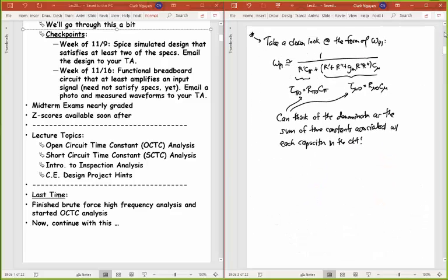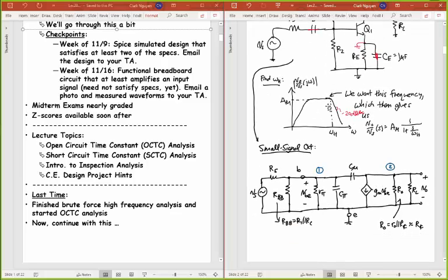We're looking for this frequency cutoff here, the high frequency cutoff. Maybe I'm not drawing it so it looks like that, but this is minus 20 dB per decade coming down here. And we want that 3 dB frequency, which we're calling omega h there, at least the radian frequency there.